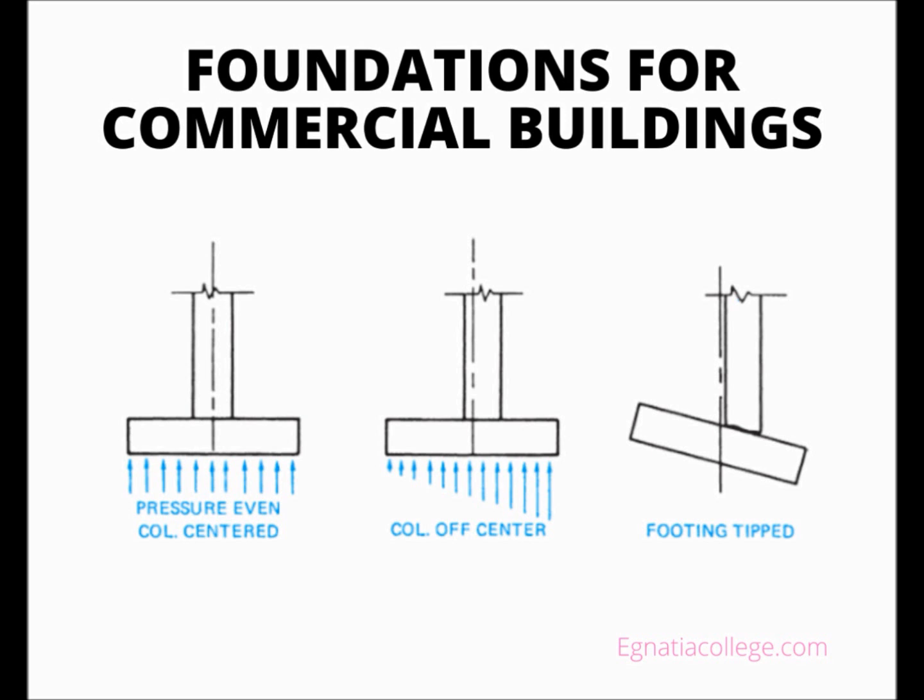These are the same elements that are found in most one- and two-family homes. The biggest difference in the foundation for a commercial building, and that for a small house, is the thickness of the concrete and the amount of reinforcing steel. There are apt to be more detailed drawings for the foundation of a larger building because of the need to describe the different sizes and shapes of footings and the reinforcement at many points in the foundation. The same knowledge is required to read the foundation plan for a large building as for a smaller one.